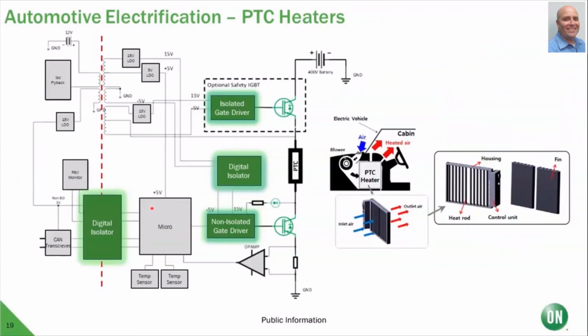There's a digital isolator that allows multiple channel communication from the microcontroller to some of the sub-circuits, an isolated gate driver to control the IGBT device that turns on to warm up the PTC heater, and additional digital isolator and non-isolated gate drivers in this application.